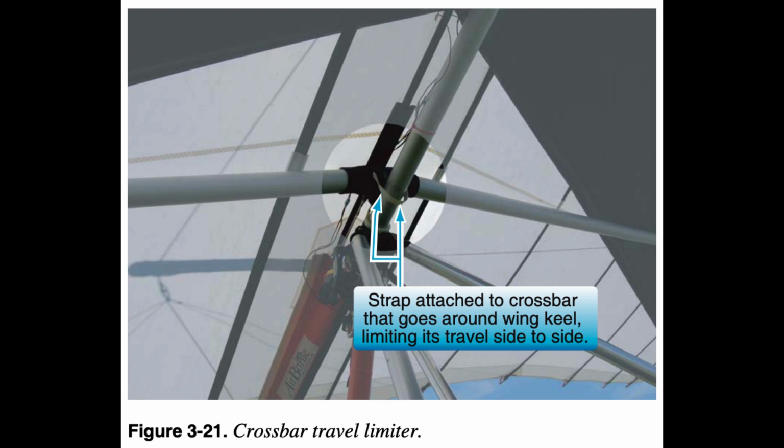Trim systems. There are a number of trim systems to relieve the control pressures for pilots to fly at different hands-off trim speeds. Ground adjustable trim allows the pilot to adjust the trim speed of the wing on the ground and remain at one speed during flight, while flight adjustable trim systems can change the trim speed in flight.